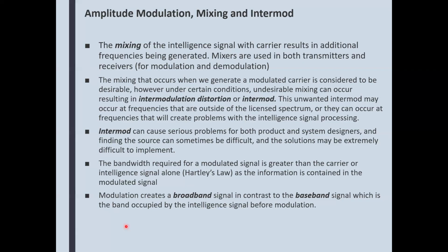It's still a medium, just like the wire, but it's different. It just blanket covers all of us and everything. So modulation creates a broadband signal, which means all channels, everything is present in the medium at the same time, in contrast to baseband, which is a time-sharing concept.